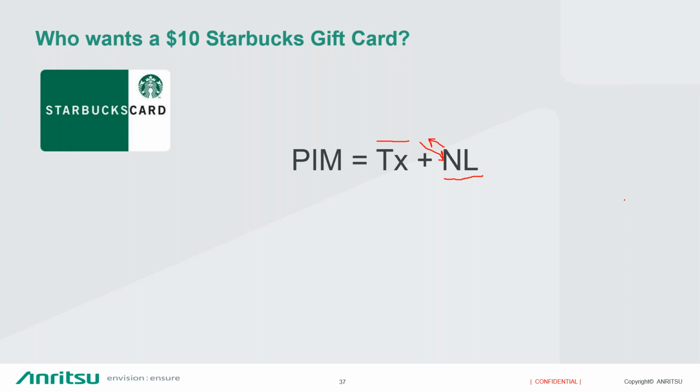A site assessment meaning, how many bands do I have? How many fibers do I have? How many antennas per radio head? What's my CPRI rate? Sometimes that information isn't available, or you have to go to the tower and look, and it looks like single mode fiber, for example.